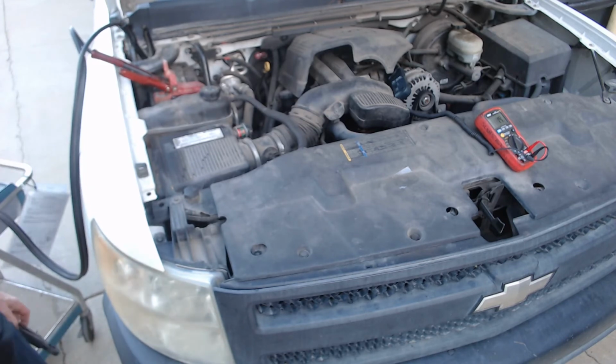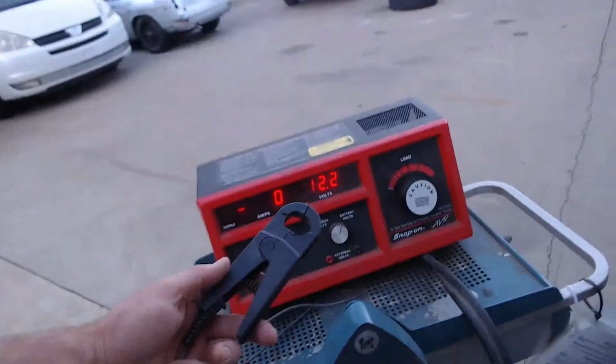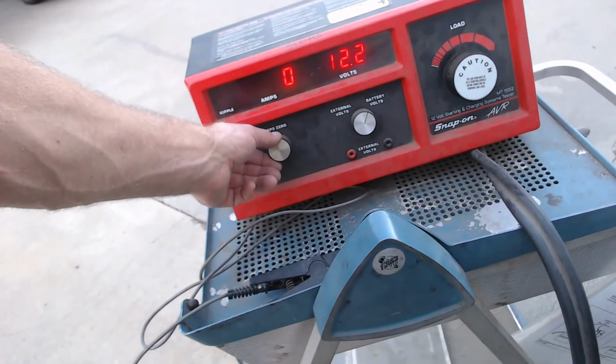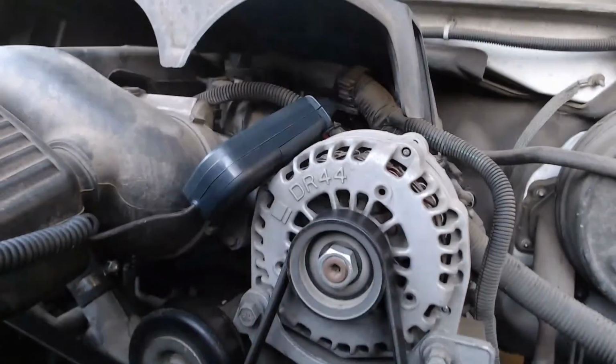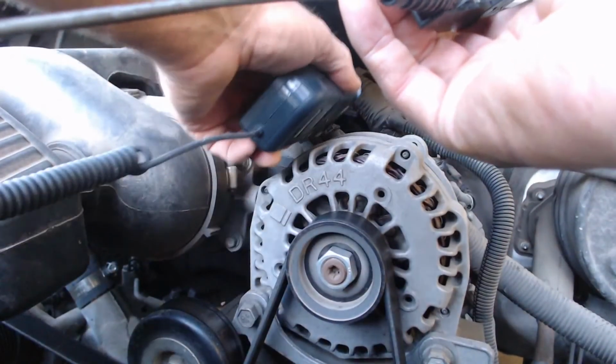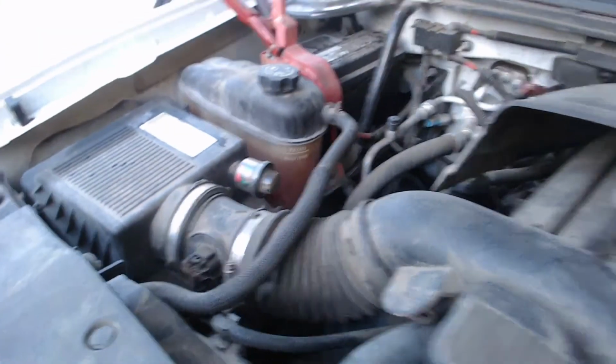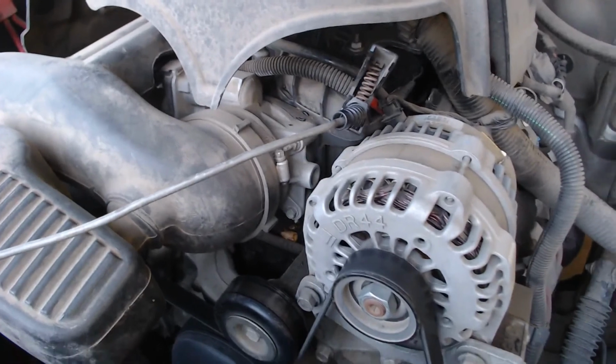Then over here on the machine, if I can pull this off and not make you too dizzy, I've got the amps connector off. And I can zero the ammeter. I had it zeroed, but I'm just kind of showing you I can adjust it down to 0. And then the most accurate way to do an alternator output test, as I pull the machine over, is come over here to the car and get this inductive lead around the battery or the alternator output lead. I can put it around the battery cable over there at the battery. But if I put it around this guy here, I'll get the most accurate output.